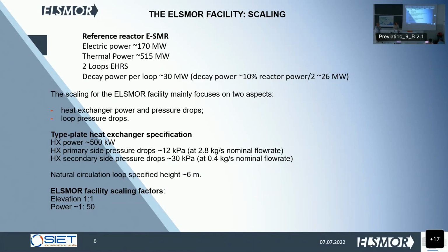So we have built another heat exchanger, fully instrumented with accelerometers, strain gauges, and so on, and we have done vibration tests. For the moment, we have done tests in air, but we will do tests also in water.